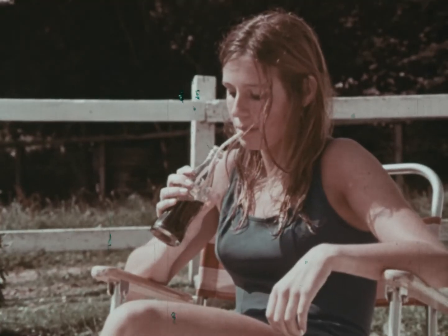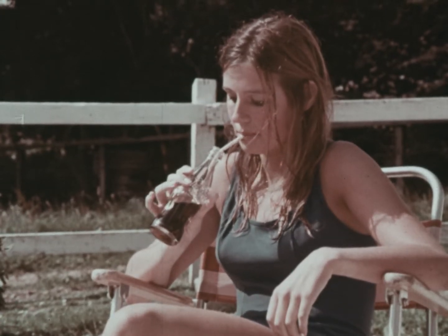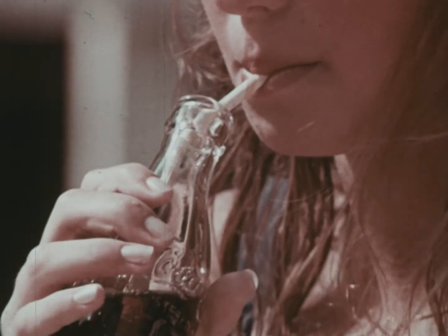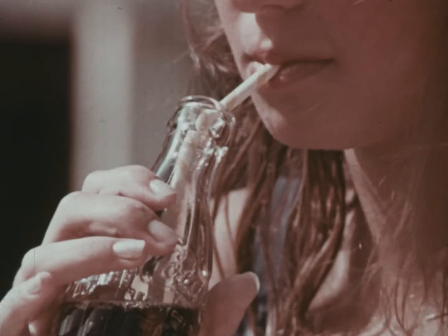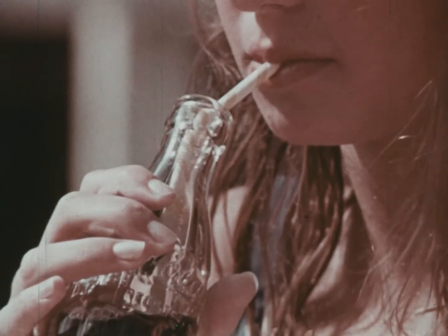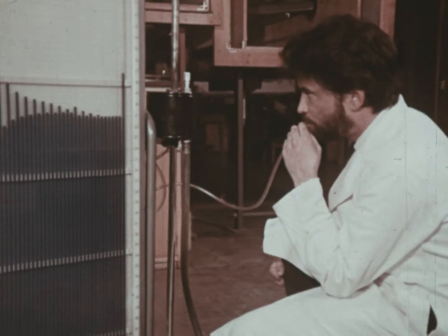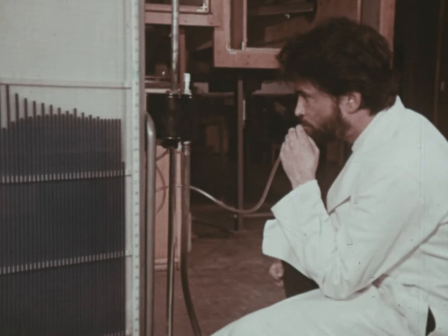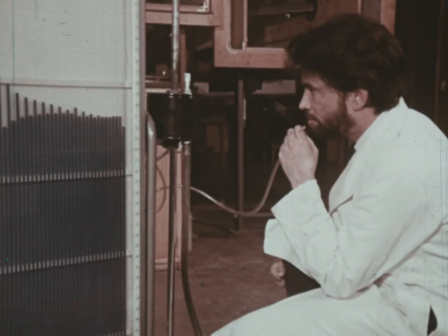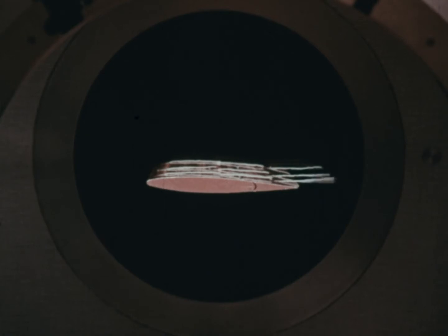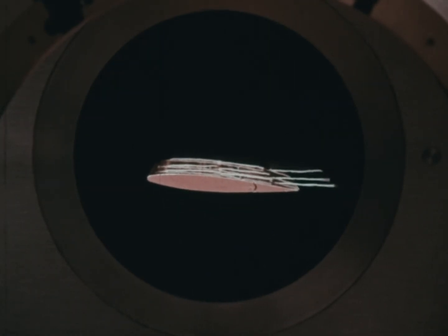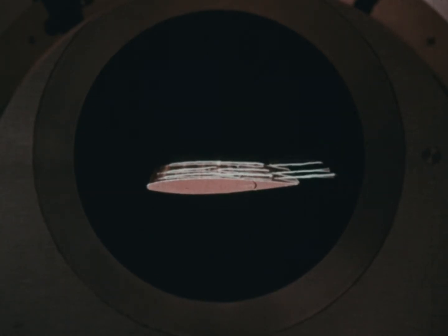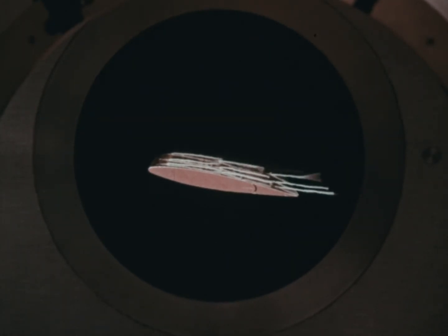When we drink through a straw, we suck in to reduce the pressure in the straw, and this causes the liquid to rise up inside it. If we alternately blow and suck on a manometer tube, the same thing happens. And so, if we put the wing section into a wind tunnel, any changes in pressure acting at right angles to the wing surface will be shown on the manometer tubes. Each tube is attached alternately to the upper and lower surfaces.